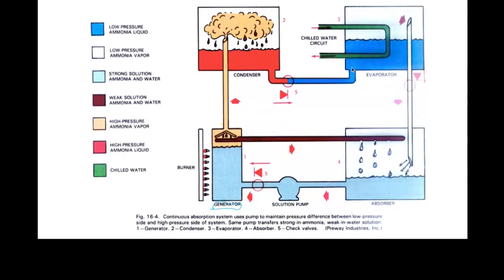And I like starting with the evaporator, okay? Maybe we'll start with the expansion valve. So here's our metering device. Now, maybe it's low side float, because this is likely a shell and tube heat exchanger. And what we've got, chilled water. So we're going to have a chilled water pump, and/or brine, or whatever it happens to be. If it's an industrial refrigeration system, maybe it'll be a brine that we're chilling off to -30 or something like that. Anyway, in the evaporator, we've got R717, and that R717 is boiling under low pressure and low temperature, and the vapor is cooling off the chilled water, of course.